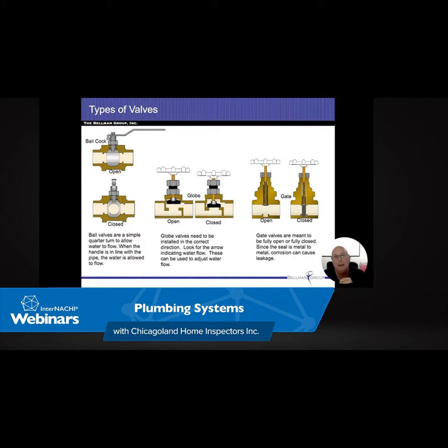Polybutylene is what we're looking at here. It comes in both stiff and the bendable or flexible stuff. The only time I really see this being used is on lawn sprinkler systems, and even that, around here, a lot of people still like to go with PVC for their lawn sprinklers. The connections that they had with the polybutylene and ethylene, where the plastic starts to break down and becomes soft, rubbery, is where the temperature rating comes from.